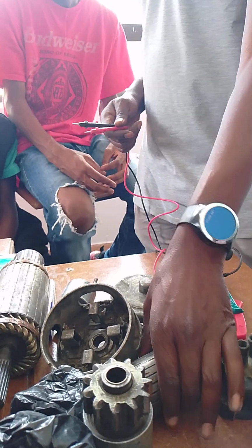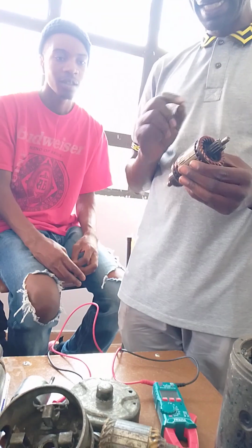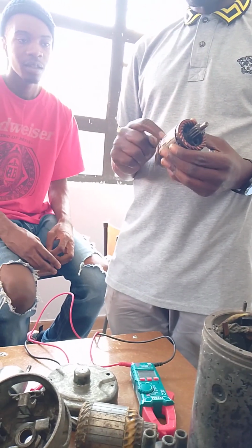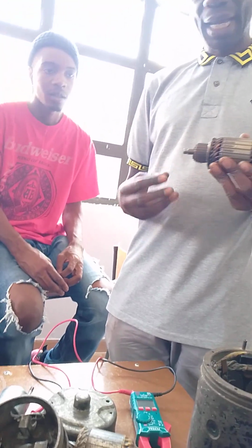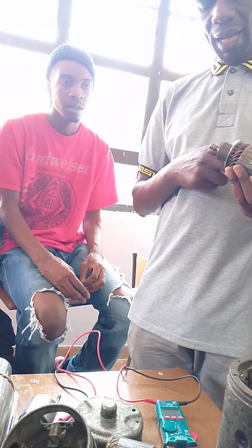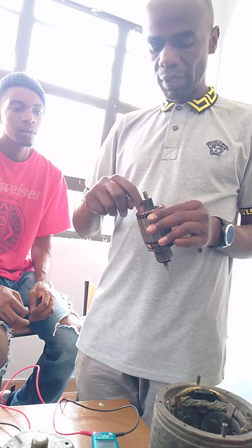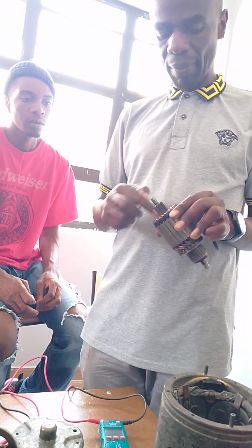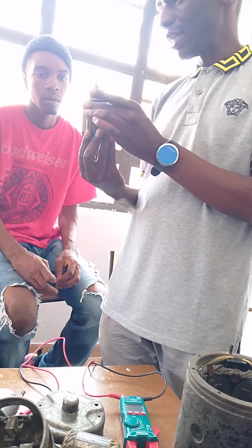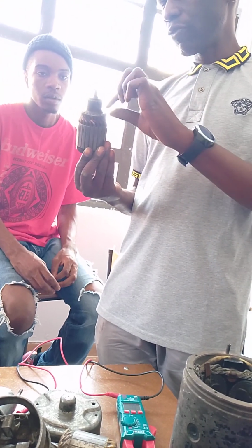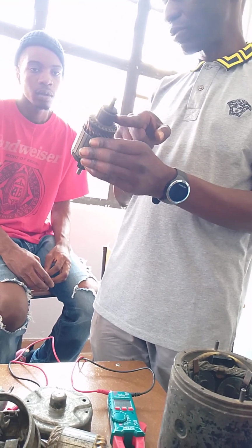Alright, let's look at the armature. The armature here has wire, wound as a net, and you can connect to a segment. This we call the commutator. Each wire goes to a specific segment, and at the back they are folded and connected. My wires are all interconnected. This one is a net, so that current flows through one wire and comes out through the other, connected to the negative.